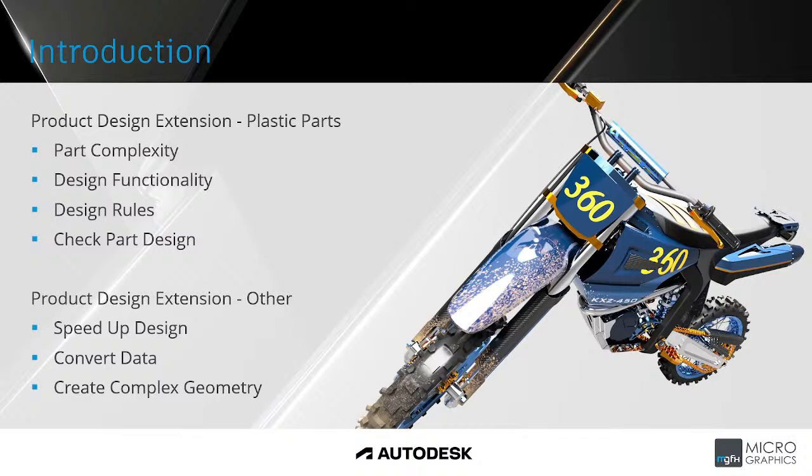And at the end of it, we would be able to run checks that would check the part design for specific issues related to the part itself and in the plastic environment. Let's say we're looking at molding, then we can look at that part with respect to molding and see, are there areas that are too thick, are there areas that have knife edges, are there areas that don't adhere to those design rules that were specified.